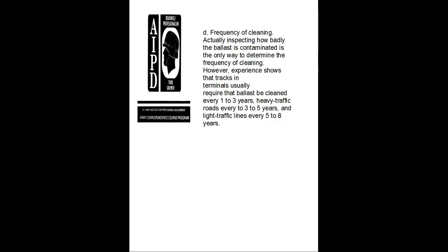However, experience shows that track on terminals usually requires the ballast to be cleaned every 1 to 3 years, heavy traffic roads every 3 to 5 years, and light traffic every 5 to 8 years.